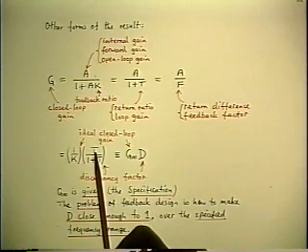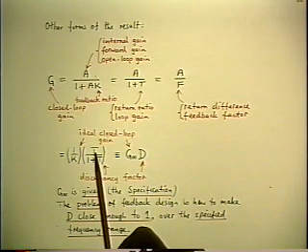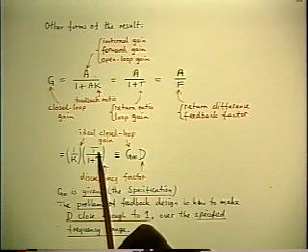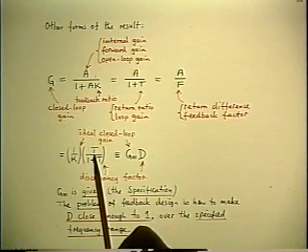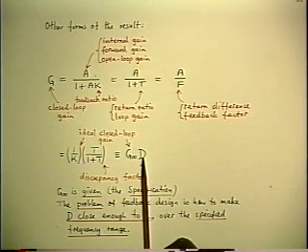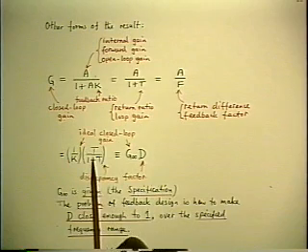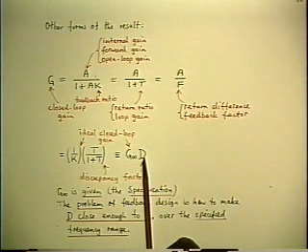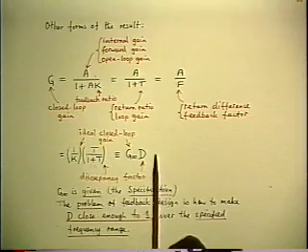Because t is going to go to 0 eventually at infinite frequency, regardless of what else you do. So no matter how big you make it, at higher frequencies, ultimately t goes to 0, which means somewhere in between it crosses unity. And where t crosses unity is about where the D starts to fall off. See, if t is 10, D is 0.9. So it's still pretty close to 1. If t is 1, t over 1 plus t is already 0.5. And you're starting to deviate significantly from the ideal limit. And ultimately D goes to 0 as t does.